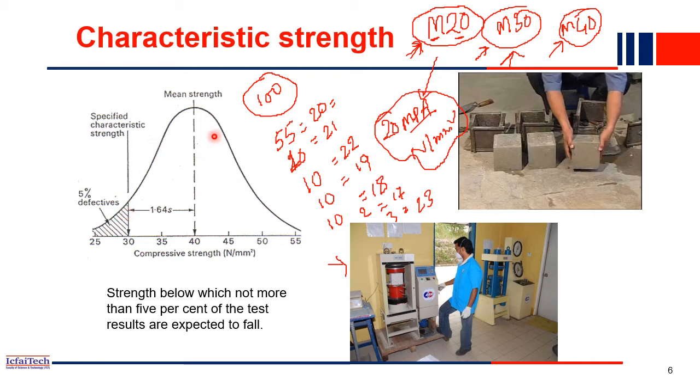Whenever we have the load, we multiply with some factor to get higher loads. For example, in a structure, load is acting 100 Newton. So while designing, we'll consider not 100 Newton, we'll consider 150 Newton is acting. So we increase 100 to 150. We design a structure where 150 Newton load is acting, although in reality the load is 100, right? But in design, we consider it is 150, for example.